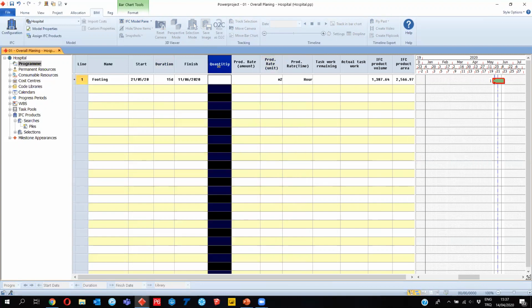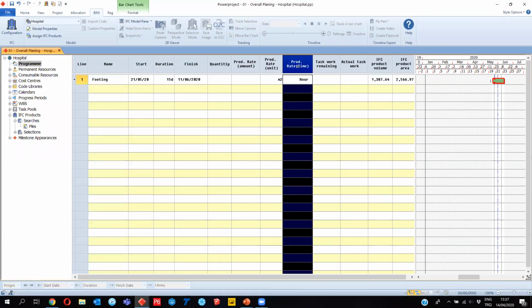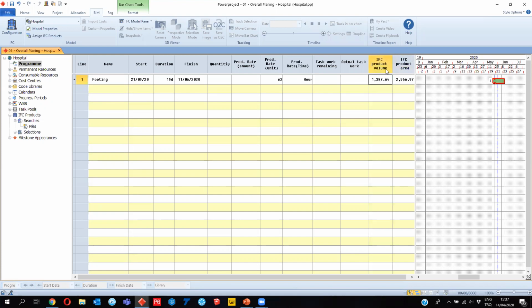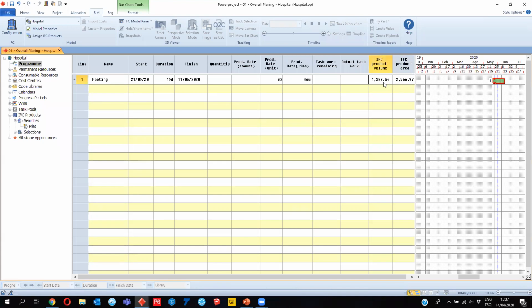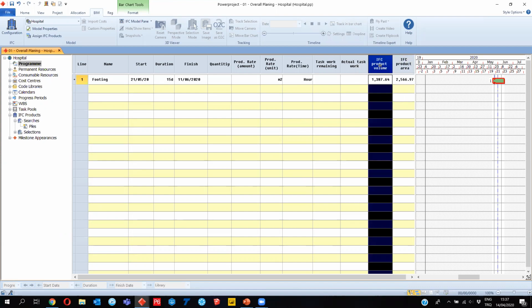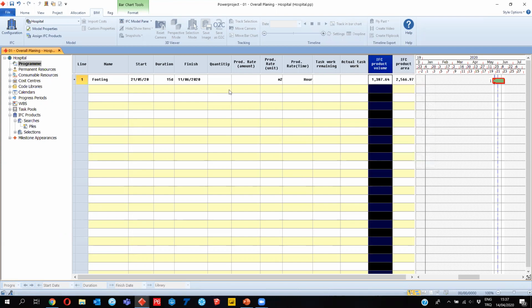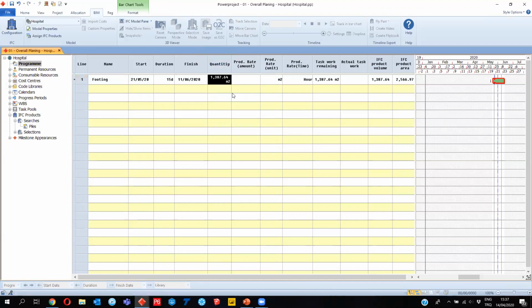So these are the quantities, product rates, product meter square or meter cube, which we can also select. And you see here all the allocated IFC quantities that come from the 3D models. So you see here, I want to use the volume. In the footing activity, we have approximately 1.4 thousand meter cube quantity. So I want to use this value. That is why I'm copying it and pasting it to the quantity column. So let's say paste values.